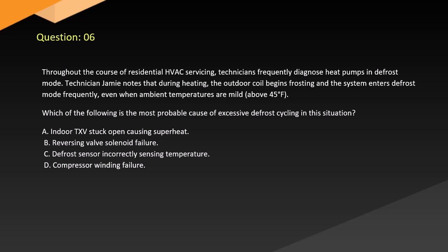Question 6. Throughout the course of residential HVAC servicing, technicians frequently diagnose heat pumps in defrost mode. Technician Jamie notes that during heating, the outdoor coil begins frosting and the system enters defrost mode frequently, even when ambient temperatures are mild, above 45 degrees. Which of the following is the most probable cause of excessive defrost cycling in this situation?